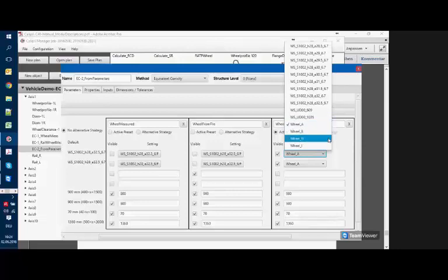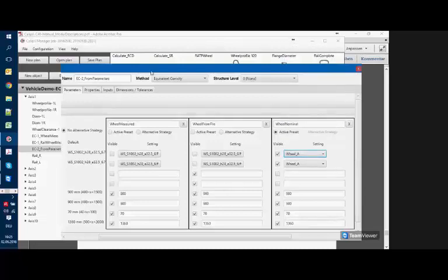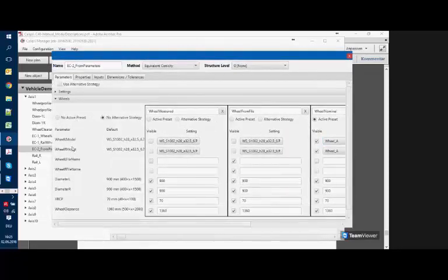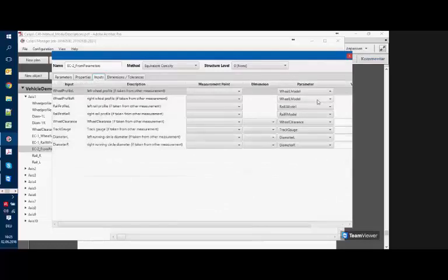So in the rules on how to implement the equivalent conicity calculation, these four reference models are also included to prove that the results are as expected, so that our algorithm calculates the equivalent conicity as it should. Additionally, you have the wheel profiles which are present in our wheel shop model. Because they are already there, we also added those to the conicity method.